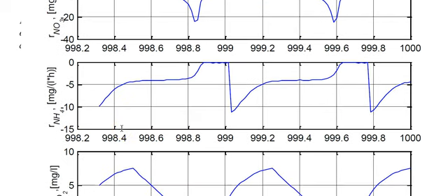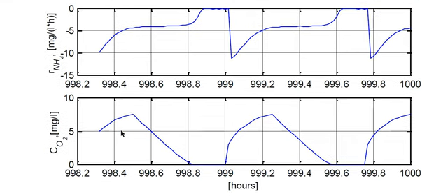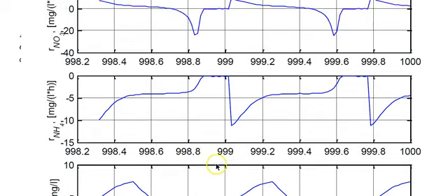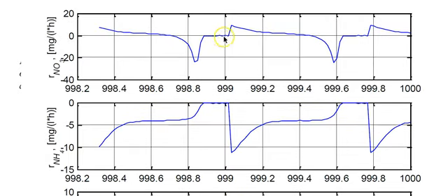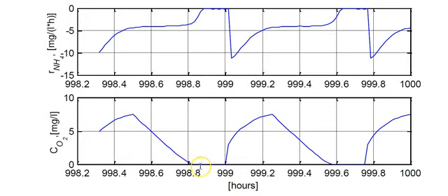But what we also see here is kind of the explanation why it's very useful to have really short aeration cycles. For instance, here, oxygen goes to 0, and it remains there for a while before air is turned back on. And during this period, we would think maybe that we have efficient denitrification. But not really. We see here, nitrate removal has stopped because there simply isn't more nitrate there to be removed. So in essence, some of these periods when we have long cycles is just waste of time. That's why keeping very short cycles is the most efficient.